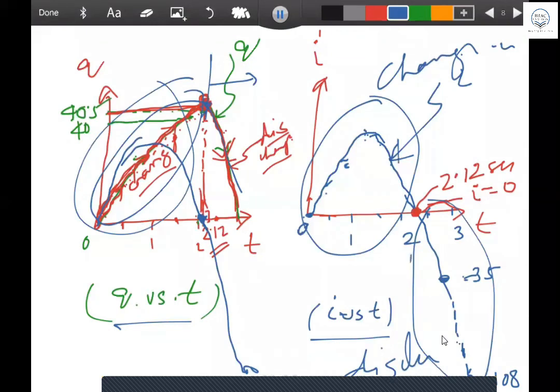And over here you can see throughout it is positive. So the current is positive because the battery is charging here. You understand? I think everybody got the point why it is negative current: because at discharging time, the battery current direction is opposite. That's why negative current is coming there. And charging time is positive. You can ask me the question here, sir, how come it is a curvy thing here? That can be a good question.